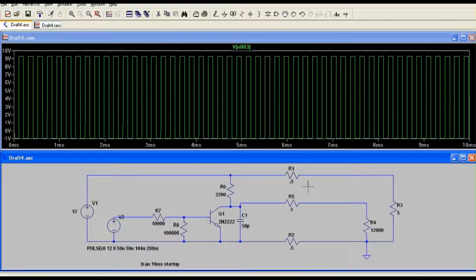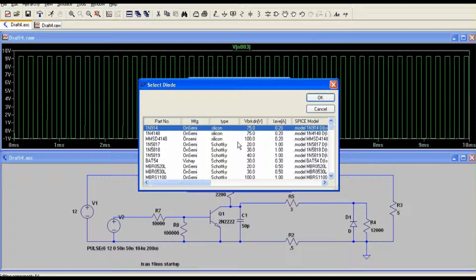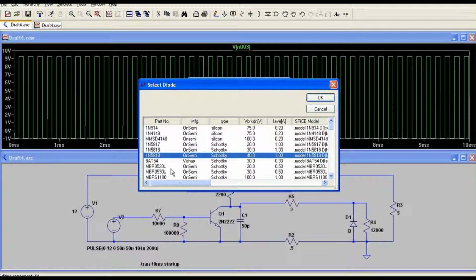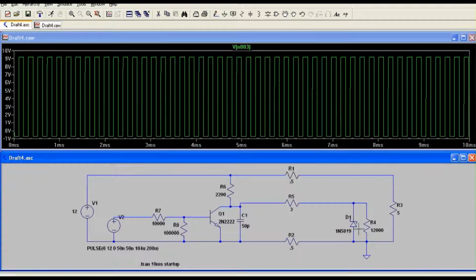Okay. Back to normal. Alright, the next thing then is we can clamp that negative voltage by putting a diode in this orientation, because you remember when we're measuring here and looking at this point here, we're seeing negative. So when that happens, that one volt can get clamped by this diode, and we want to choose something with a low forward voltage, like some sort of Schottky. 1N5819 is going to be overkill, but for illustrating the purpose, it's not so bad.